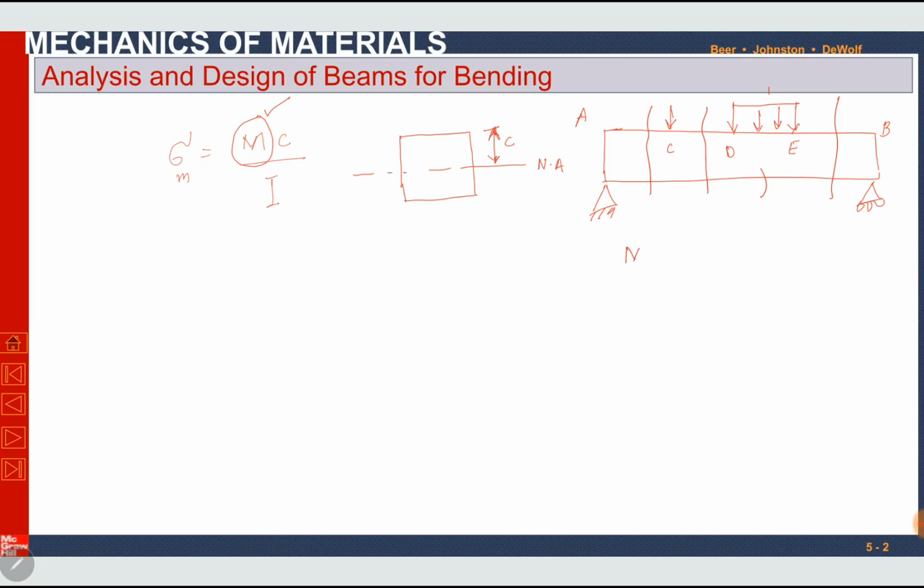So bending moment will be a function of length. X is length. So there will be a variation in the values of bending moment. It can be minimum at some point and maximum at some other point. So the maximum value of bending moment is important for us. If we put the maximum value of bending moment in the expression above, the maximum absolute value, it can be either negative or positive. We will just take the positive magnitude of it.